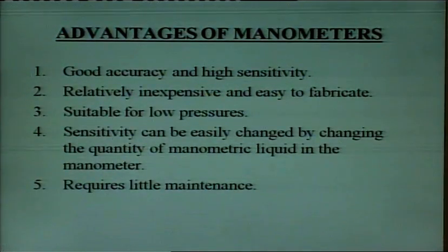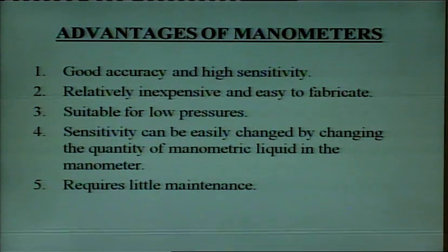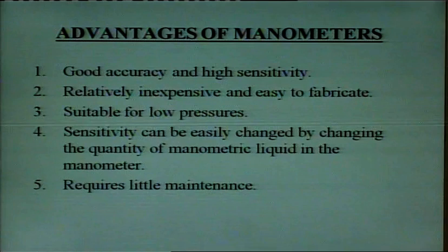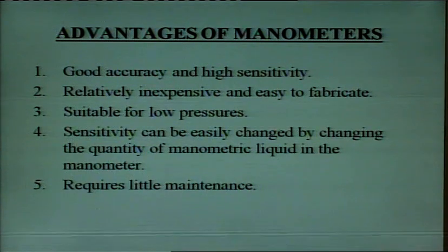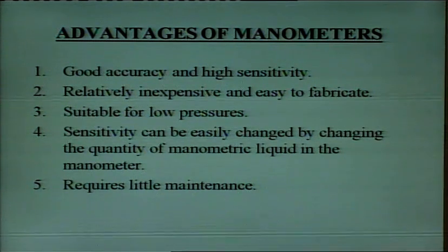Then we come to the advantages of the manometer. Good accuracy and high sensitivity; relatively inexpensive and easy to fabricate; suitable for low pressure. Fourth, sensitivity can be easily changed by changing the quantity of the manometric liquid in the manometer. It requires little maintenance.